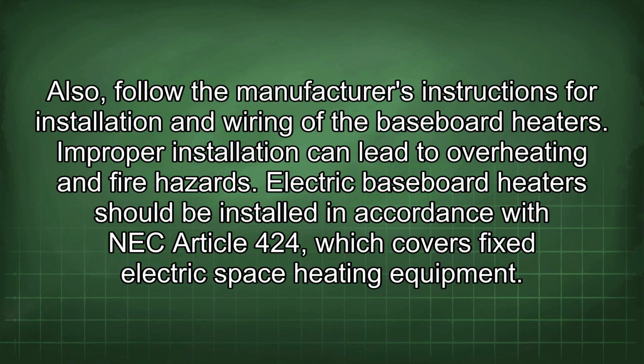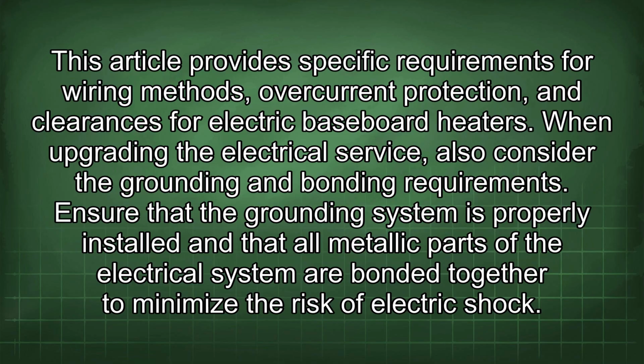Also, follow the manufacturer's instructions for installation and wiring of the baseboard heaters. An improper installation can lead to overheating and fire hazards. Electric baseboard heaters should be installed in accordance with NEC Article 424, which covers fixed electric space heating equipment. This article provides specific requirements for wiring methods, overcurrent protection, and clearances for electric baseboard heaters.